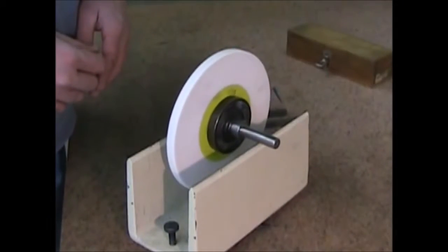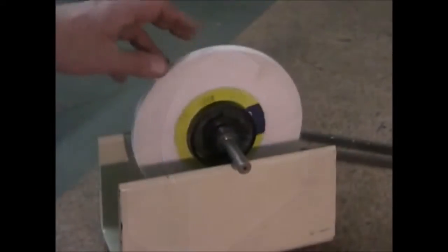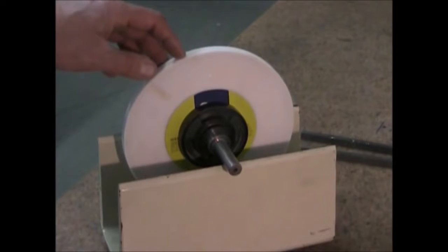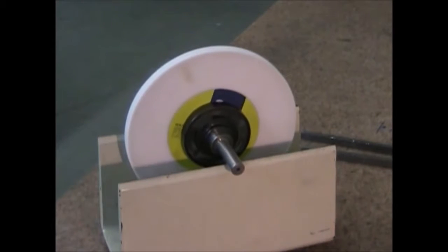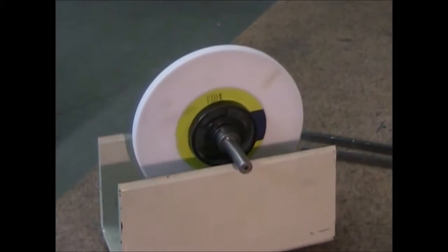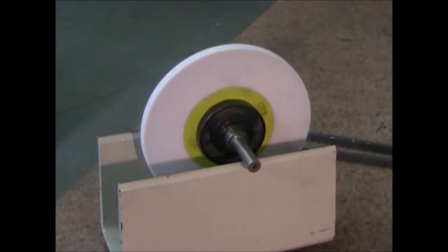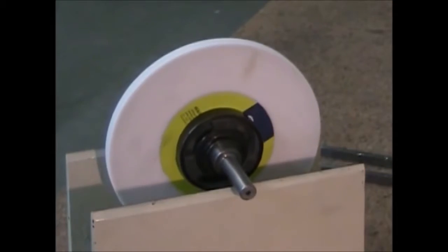When performing grinding, the efficiency of the grinding wheel must be maintained. To do this, the grinding wheel must undergo balancing, truing, and dressing every so often. Balancing removes vibration at high rotational speeds, while dressing breaks off dull abrasive material from the wheel. After dressing, truing ensures that the wheel remains cylindrical and round.